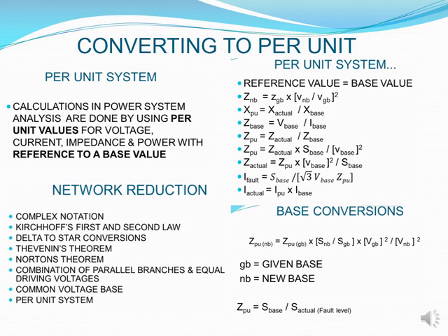Now we look at conversion of our systems into a per unit system. So firstly, our per unit system: we do calculations in the power system analysis using them, where we replace your voltage, your current, your impedance, and your power with whatever is the reference base on them.